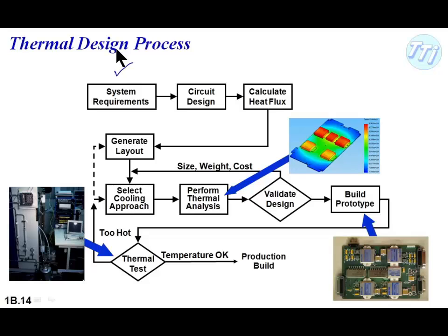What do you want? Yeah, so defining system requirements up front is so important for the thermal designer to know what techniques to use, what temperatures they should be striving for. What kind of reliability do you want out of this? Is this a device that's going to be used for a year, or is it going to be 10 years?